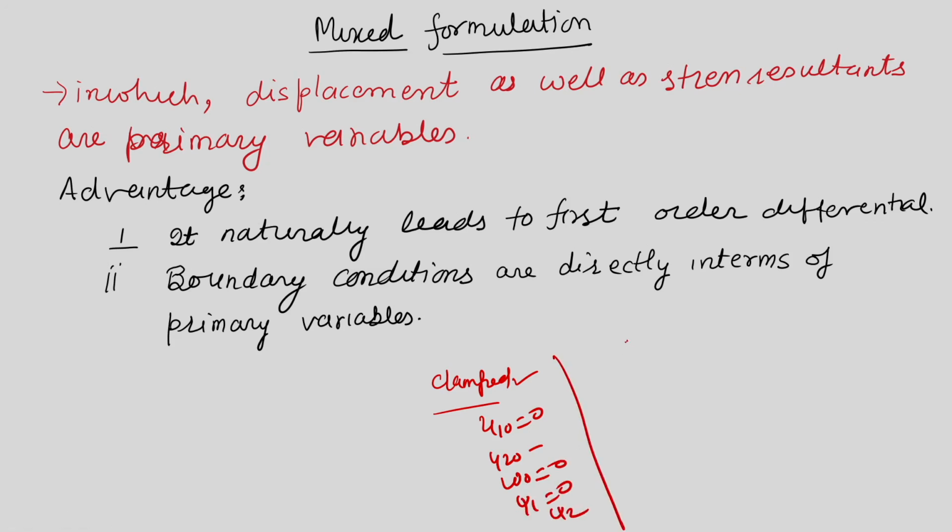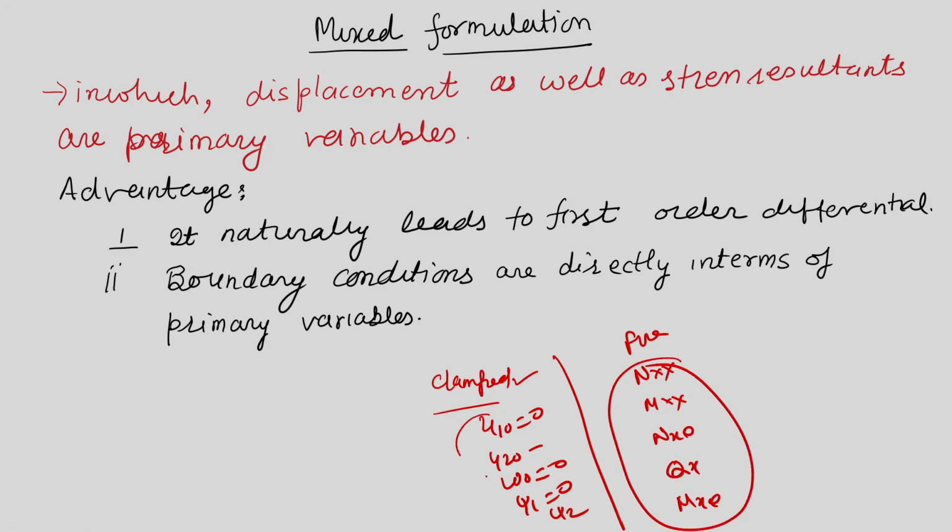But if the edge is free, then it will be nxx, mxx, nx theta, qx and mx theta. These are not our primary variables in the displacement formulation. So, we have to satisfy these stress resultant conditions through the shell constitutive relations, which is again slightly tedious. But in a mixed formulation, these stress resultants are primary variables, so we can directly satisfy the boundary conditions.